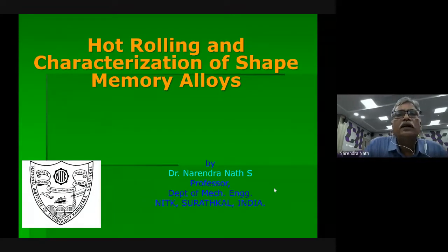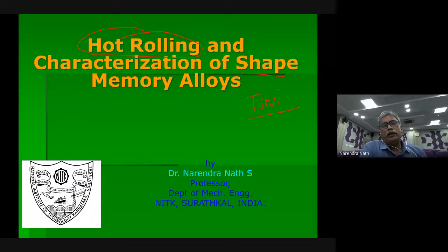And today's afternoon talk is on hot rolling and characterization of shape memory alloys, and why hot rolling. Normally with these shape memory alloys, if it is titanium nickel based, when we want to give any new shape, for example a rod or a plate, cold rolling is not a solution. Cold rolling will crack automatically. When you roll it, it will crack.